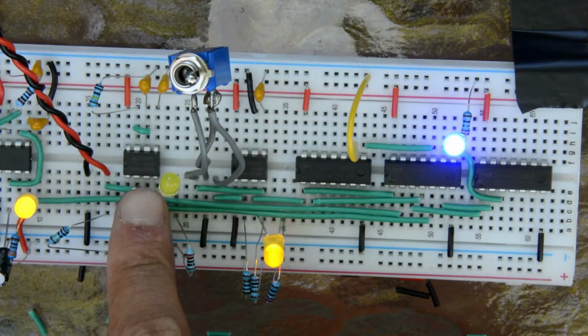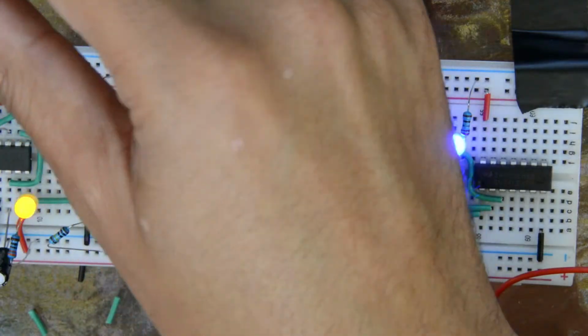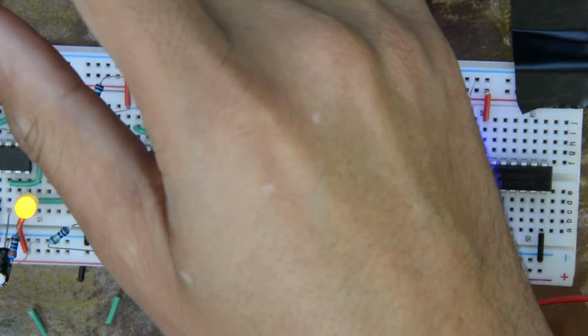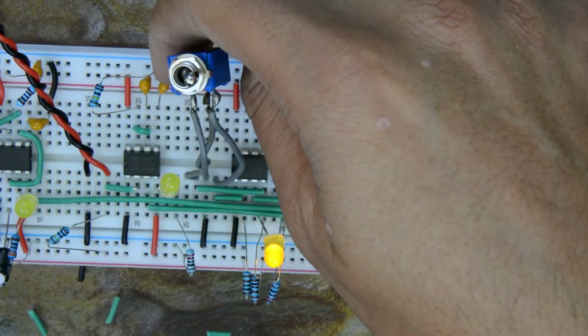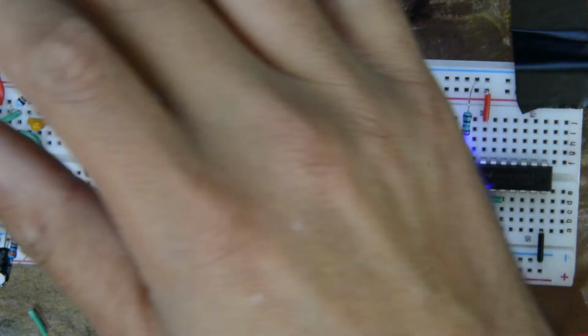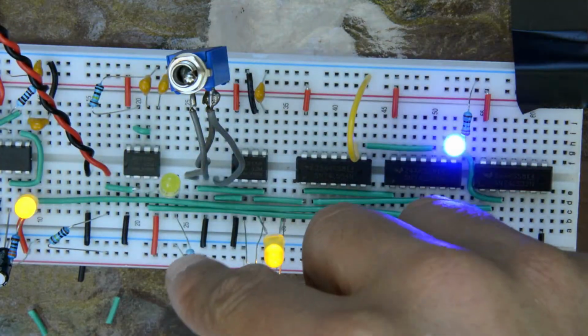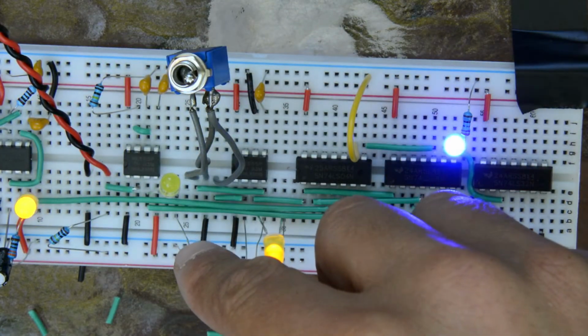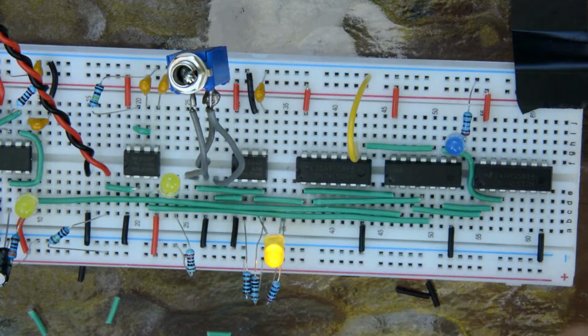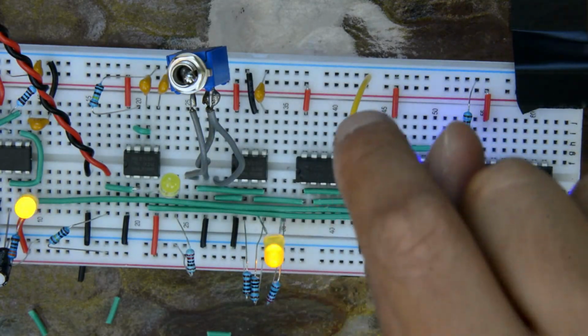So the only reason why we actually need a 555 for just a simple button is just for debouncing, so that we make sure that there's some amount of time that it takes for this capacitor to empty, so that we don't accidentally hit it multiple times. If you look at an oscilloscope, you can see that this is actually a problem, and that if you want to only step once, you definitely need debouncing.